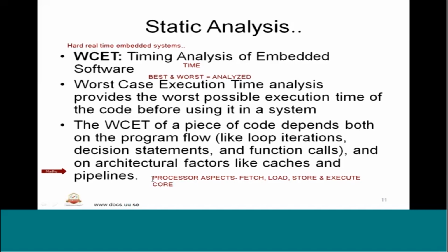So definitely a few instruction cycles are involved. Those need to be analyzed in terms of how many instructions a line of code, a group of lines of code, the entire program or a piece of function requires. So it is very important to have worst case timing analysis in embedded software testing.